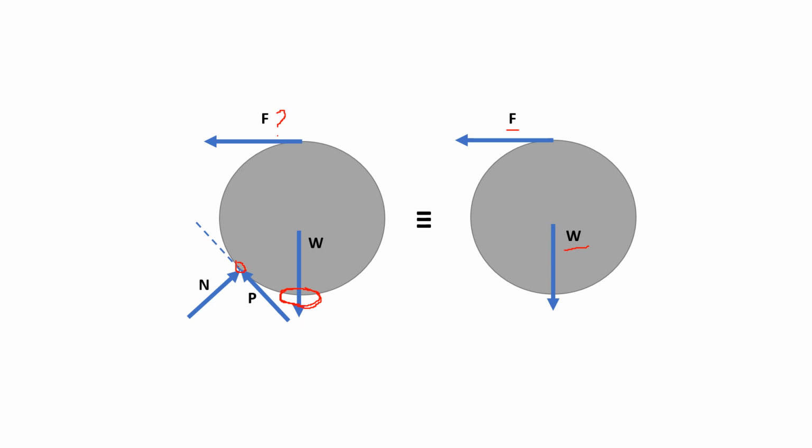Note that the wheel is subjected to force at 3 points only: here, for force F, at the center of the disk for W, and at this point here, where the wheel touches the indentation in the ground. So the wheel is a three-force member, even though it can feel 4 forces here.